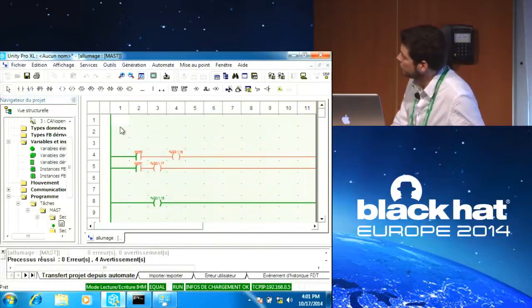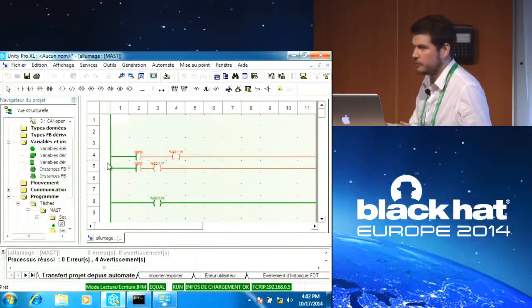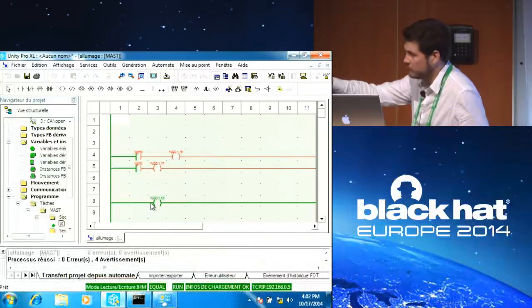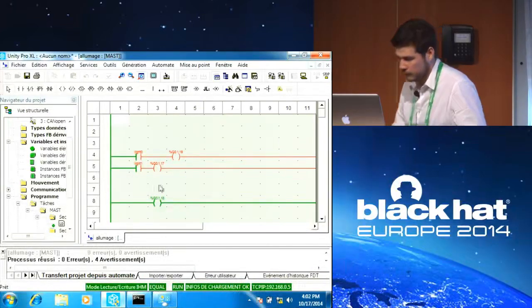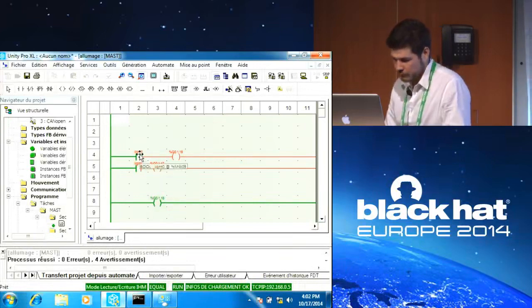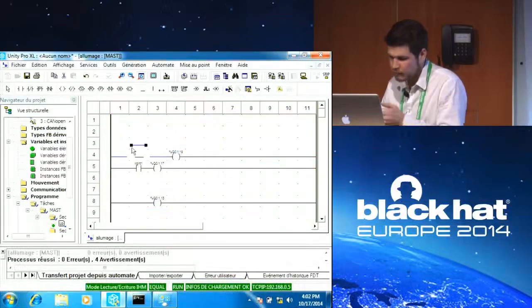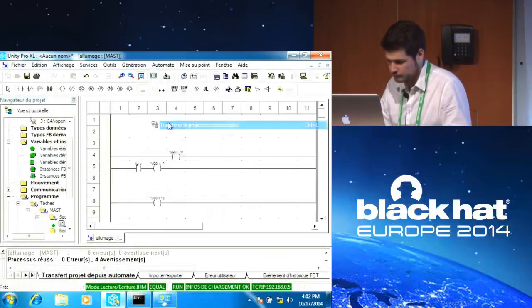As you can see, there are some lines that are green, the other ones are red. Basically, green means electricity is flowing, and red means it's not. So, for example, here, one light is lit because I just put this output to on, and the 2 others are switched off because light 0 and light 1 are set to 0 at the moment. So basically, if I just delete this one, that's ladder logic, as I was explaining before. Now I can transfer it to the PLC.